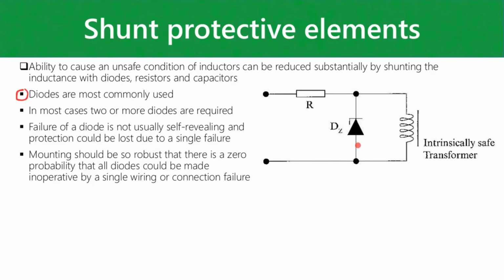Now this is actually very helpful for just protecting circuits in general, and not necessarily just to make a circuit intrinsically safe. So essentially what can happen is, this can even be the coil, not just of a transformer, but also of a relay. If that relay coil is de-energized, remember, you had a magnetic field on that coil. Now with the magnetic field collapsing, it's going to continue to push current in the same direction that it had been flowing originally.